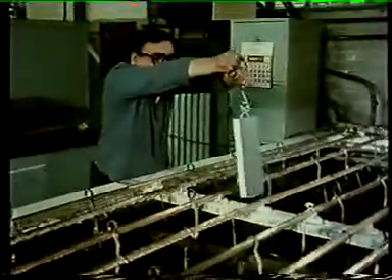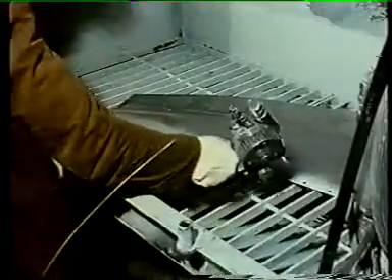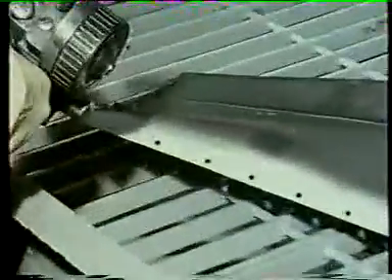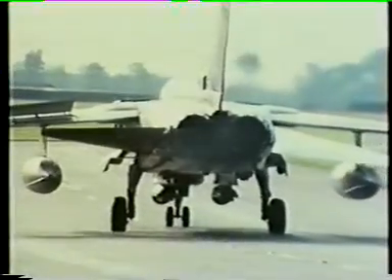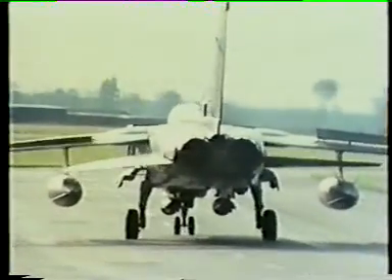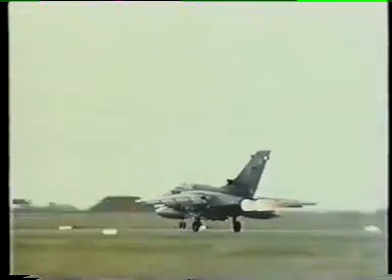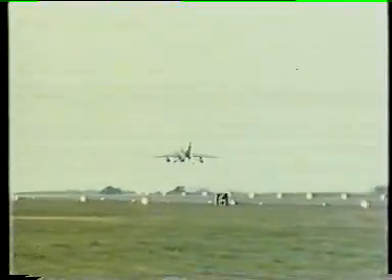Other treatments used include cadmium and zinc plating and zinc or aluminium spraying. These either reduce the galvanic potential between the metals in contact or provide a sacrificial coating which is eaten away in preference to the base metal. However, despite good design, use of suitable materials and effective methods of protection, corrosion will inevitably occur due to a variety of operational factors.